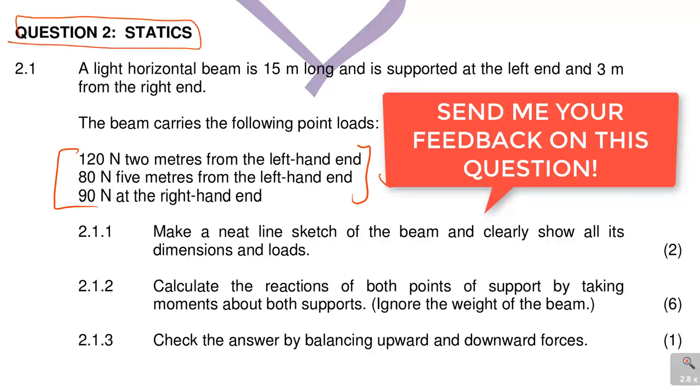Then it says make a neat line sketch of the beam and clearly show all its dimensions and loads, 2 marks. Calculate the reactions at both points of support by taking moments about both supports. Ignore the weight of the beam, a good 6 marks. Then check the answer by balancing upward and downward forces, and then you do the same. We've been looking at all these. We've covered that, we've covered that, we've covered that. Now I want you to try this question.